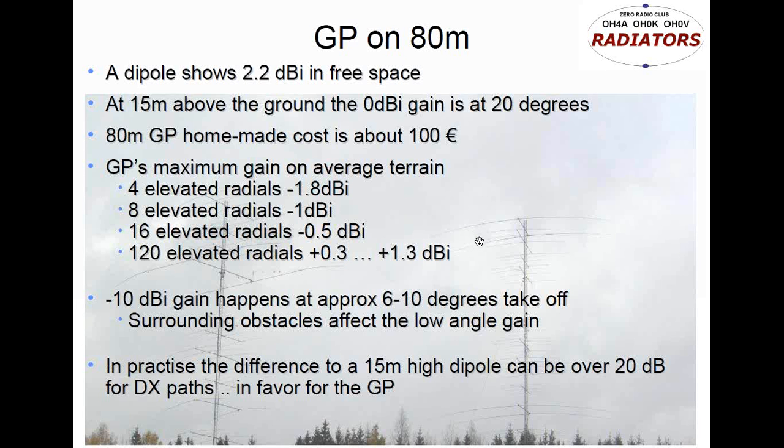I have verified this. But if you don't have the possibility to have a horizontal antenna up somewhere like 30 meters or 100 feet, then this ground plane is going to be much better. So if you have a horizontal antenna up only about 15 meters, or you have a ground plane, your ground plane is going to be much better. But you're going to be losing to guys that have horizontal antennas up about 30 meters or more.